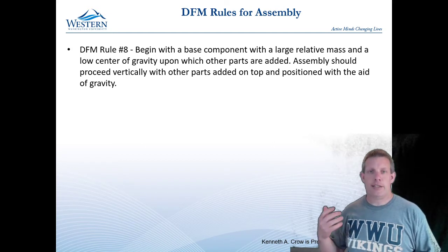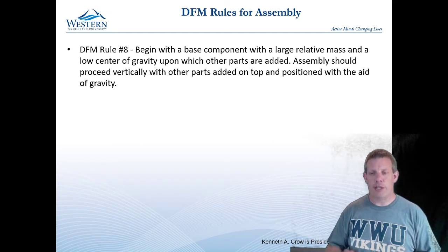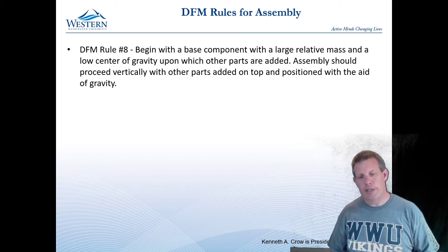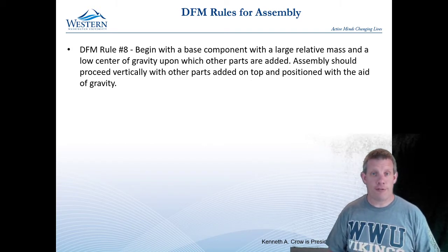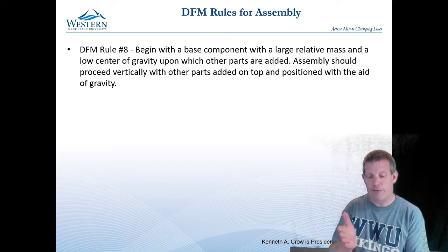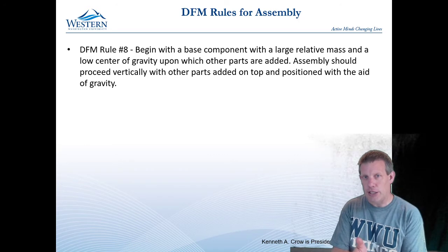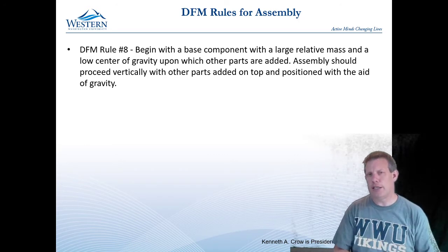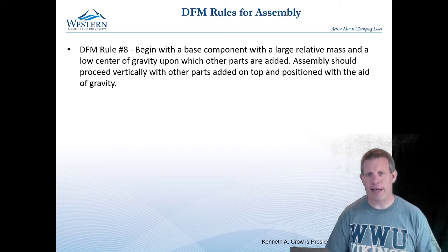Now, that is the fastest way, if you can do that, if you can put it there and have gravity hold it in place. One thing that we'll often find in fixtures is that we have to have more precision and more location than we can depend on gravity to provide, especially if we're not completely sure that our incoming materials are exactly flat every time.